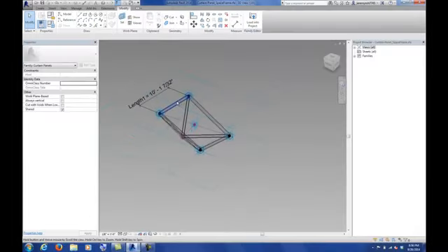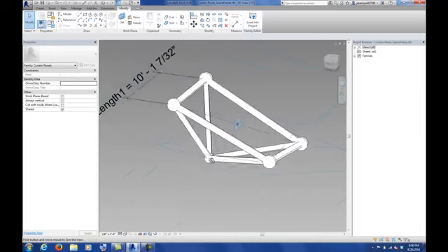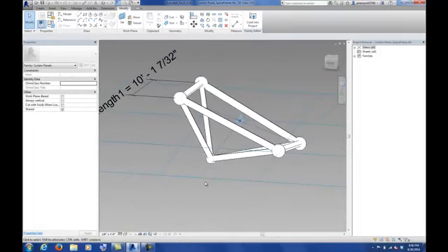When we talk about folding panels, like I have been alluding to, we will be doing all of that in an adaptive generic model family, so we can make all of our adaptive points and actually extract any of our reporting parameters that we want in the near future.